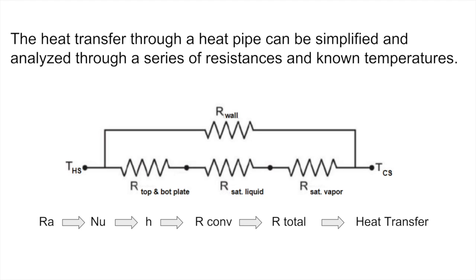There is a resistance for both the top and bottom cap of the tube that are identical, making them easy to combine. All the material properties for these resistances were easily found in tables, making the conduction resistances straightforward to find. The convection resistances needed a heat transfer coefficient, however.